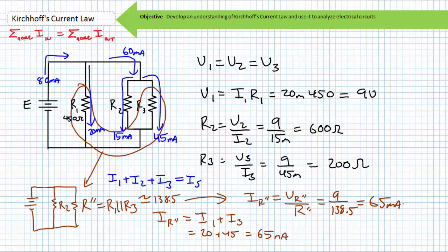This is exactly what we came up with using the quick and easy KCL equation and our revisualization of our parallel circuit as a highway, in this case having a single exit ramp servicing both R1 and R3. This is the tremendous advantage of KCL in contrast to some of the previously discussed circuit analysis properties, and why it is my weapon of choice. It is both visual and self-evident. Redraw the circuit in any fashion you see fit, and just stay organized. The math should be trivial, and importantly, the math will save you time.